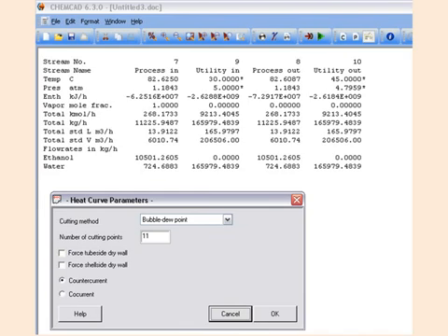The next menu is the calculated value of our utility stream. As you can see from the utility end, which would be stream 9, our total flow in kilomoles per hour of cooling water would be 9,213 kilomoles per hour. Now we're going to look at how we're going to introduce the cooling water and the vapor into this condenser. And you may not understand the reasons for it right now, but a countercurrent heat exchanger is the most effective use of area, so we will select that as well.